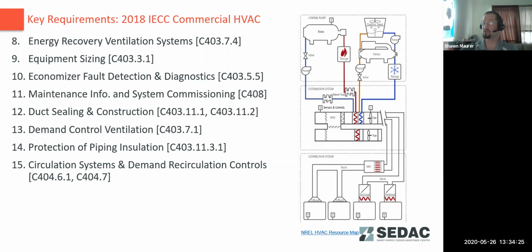If you're doing a new building, I would have to check, but I do think ASHRAE allows slightly more window area per wall area than the IECC does as far as that percentage. The IECC also has performance paths, which may also be used when you have excess fenestration as well.